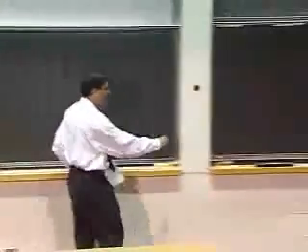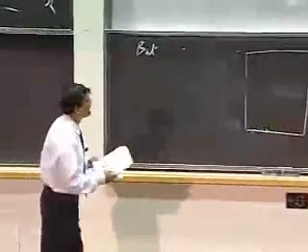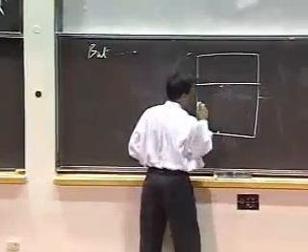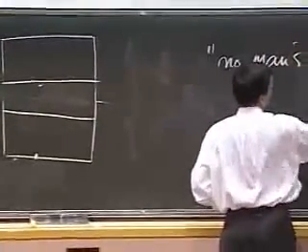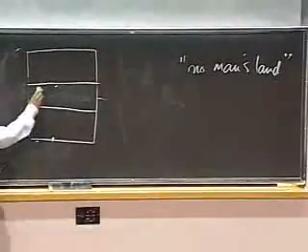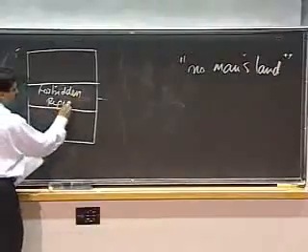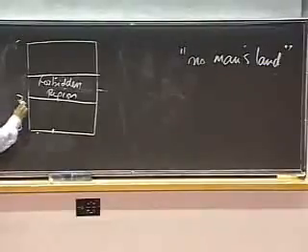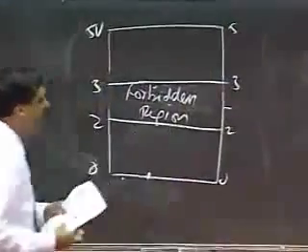To prevent the receiver from getting confused if it saw 2.5, I'm going to define what is called no man's land. I'm going to define a region of my voltage space called the forbidden region. Let's say I define it with the values 0, 2, 3, and 5 volts.